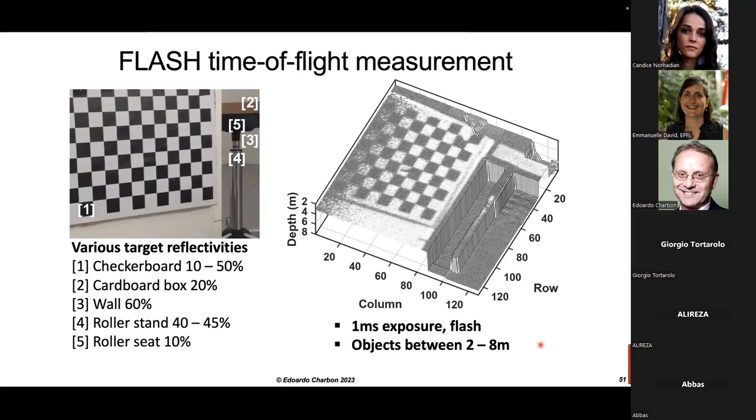So we have a paper by Karami back in 2009 that talks about that. But of course, after proton irradiation, we've observed that the number of RTS events increases. So that is an indication of an increase of traps that can be, as I mentioned, in part be reduced by annealing, and in part also reduced by electrical means, which I did not describe here.